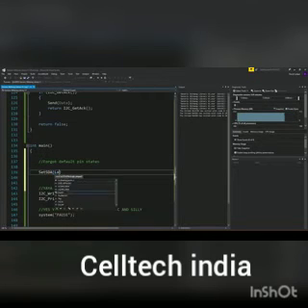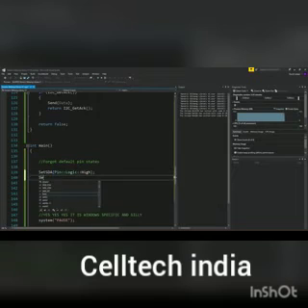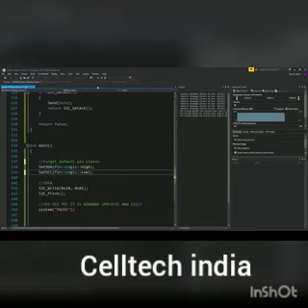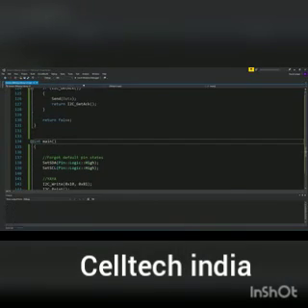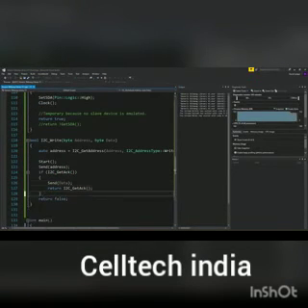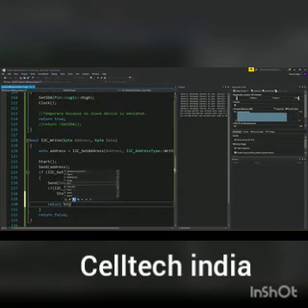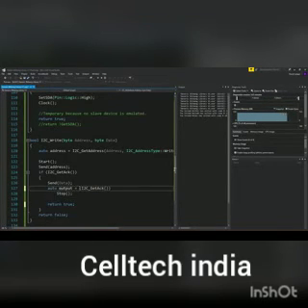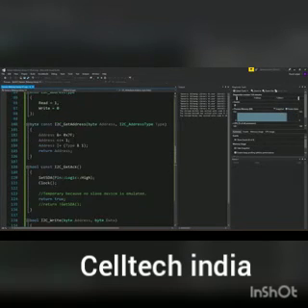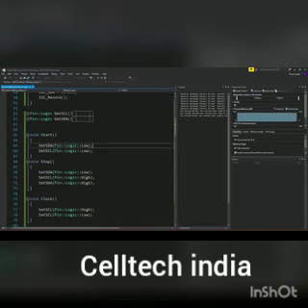Okay, so we're going to write to device 0x10 and we're going to write the data 0x81 in hex. So we should see that in the spreadsheet we're going to generate. I need to make sure that the default states of all the pins are correct. So they've got to be all default high because by default the bus is open, it's open drain. Just going to update the write routine so that it does indeed stop if it receives the acknowledgement, it sends the stop condition. I mean, it should probably do that anyway, but it doesn't matter. Okay, so now it's fixed.